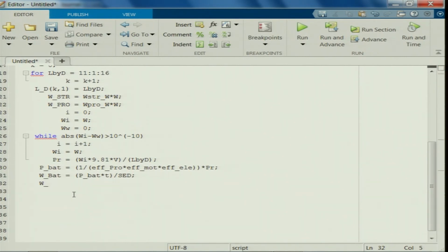So, W of the total aircraft, now the new weight of the aircraft is W, assuming the structure still remains same, structural weight plus W underscore propulsion system weight, because the propulsion system can deliver a variety of power, is it not, right. It is not considered only for single power. So, assuming this power requirement is still satisfied by this, and the structural changes because of just the increase in the battery weight is not much.